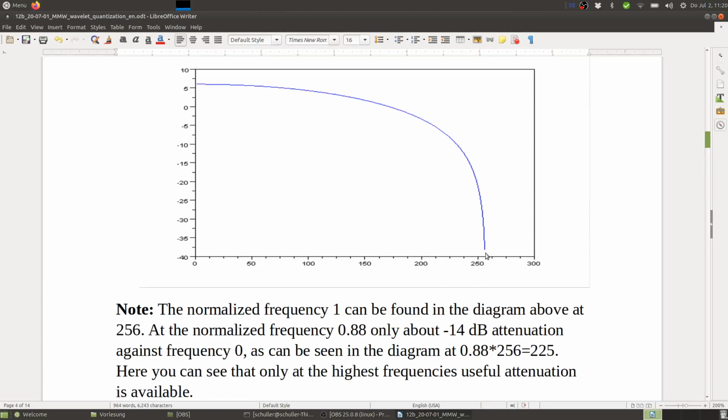So here it's now not normalized, but here we can see the subbands coming from our DFT. Right. So we chose a DFT of size 512. That means 512 corresponds to the sampling frequency, and 256 corresponds now to our Nyquist frequency, which is right around here.